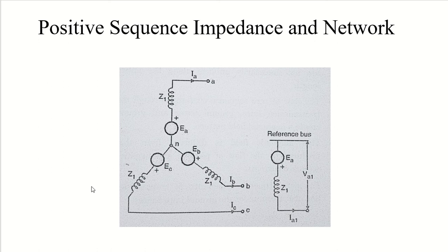Okay, so a balanced three phase voltage will imply existence of positive sequence voltage, because negative phase sequence and zero phase sequence will be available in unbalanced system only, right? So if your system is healthy, that means it is showing positive sequence. If your system is showing positive sequence response, that means your system is under healthy conditions.